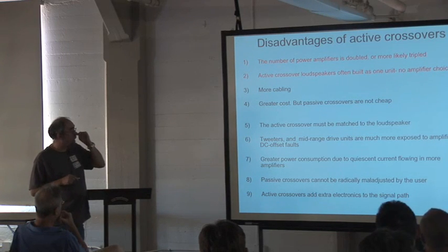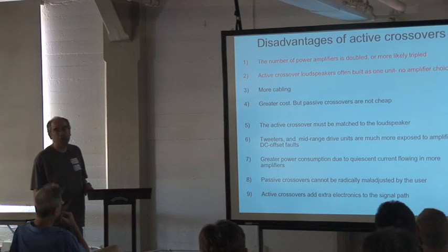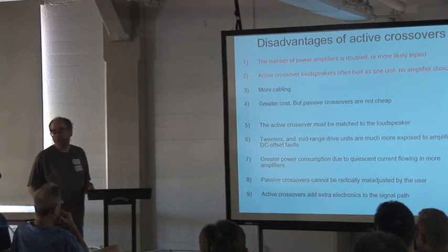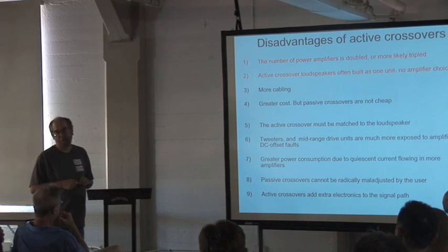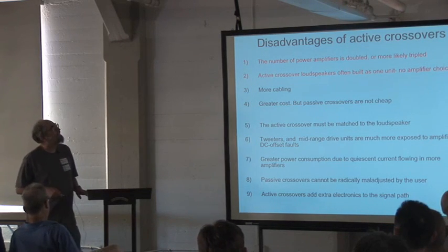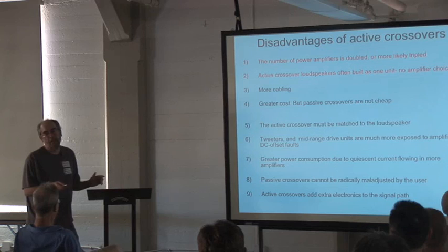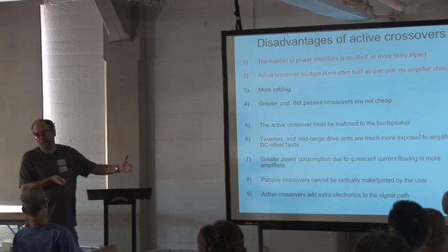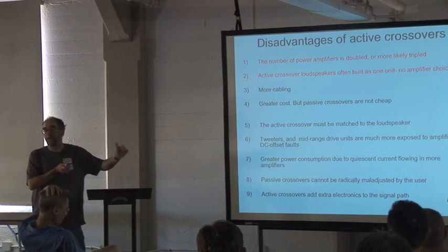Right. So going back to building the crossover into the loudspeaker, this is a real no-no because people want to choose their power amplifiers. And if you built the crossover into the speaker, then the amplifier's in there with it. And people won't believe that if you're good at designing loudspeakers, you're necessarily good at designing power amplifiers. And believe me, from some of the efforts I've seen, that's true. Really true. I've seen some shocking stuff done. So my take on that is that you want to sell your active crossover as a pair with the loudspeakers and leave the gap in the middle for the power amplifier so people can put in any power amp they like. All they've got to do is get the gain correct, and then there are no other problems.